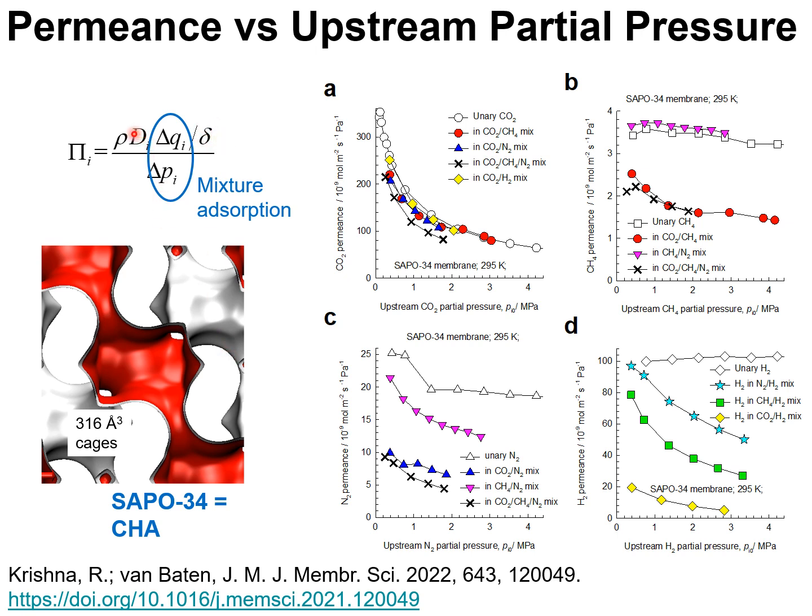We have established in the last slide that the diffusivity of any component in the mixture can be identified with the diffusivity of the pure component, provided the comparison is made at the same pore occupancy. So we don't need to worry about this. This can be estimated from unary diffusivity data that can be determined from unary permeation experiments.